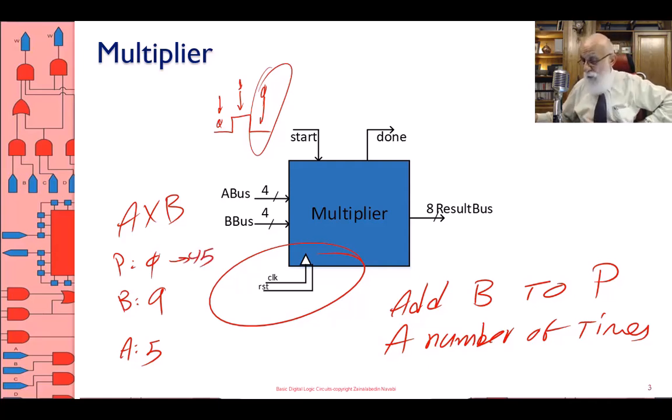Why have I chosen such an easy algorithm? Because right now, without showing you the hardware, we can all come up with the data path and the controller of this circuit. For the data path, we are doing 4 bits, right? The result has to be 8 bits. So I have a product register. I'm thinking about hardware components that I'm familiar with already.